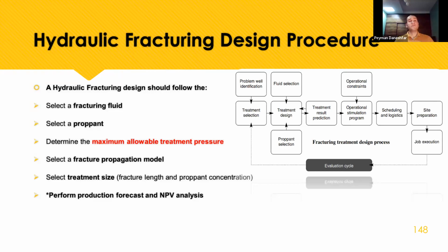because we want to check whether, if we do hydraulic fracturing, the cost is good for us or not. Sometimes the cost of hydraulic fracturing is more than the value of the oil production in a well. So we eliminate hydraulic fracturing and look for another way to stimulate the well.